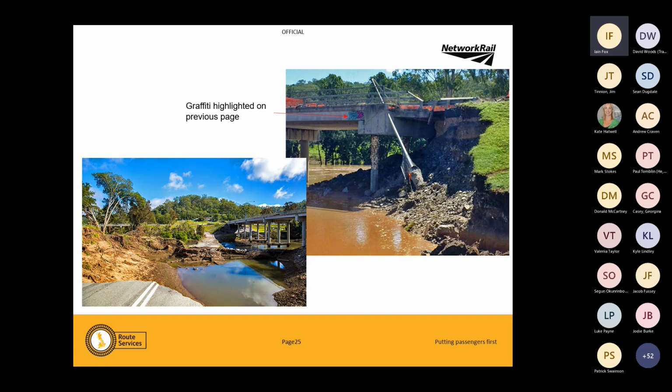It shows where it is, it shows how severe it is, it shows how deep it is. And as part of that scour monitoring program, we've actually used CFD model in all 3 structures to locate where we put the sensors, because we're that confident that this CFD modelling tells us exactly where scour happens, that we've actually put money on it and we've placed these sensors in the ground and they are live monitoring now.